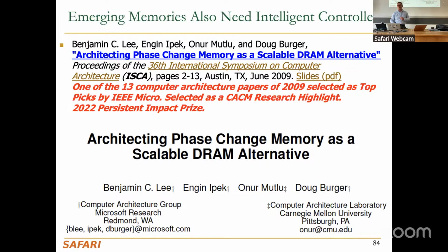But don't think that they don't run into scaling issues. All memory technologies run into scaling issues at some point. And some of these technologies have not been examined as much, have not been pushed to the limits as much. We have kind of pushed DRAM and flash memory to the limits. We still keep pushing them to the limit by reducing the cell size. But some of these memory technologies that are investigated, both in industry and academia, they start with large cell sizes. As a result, people may not see those vulnerabilities early on. The question is, what happens if you actually scale to very small cell sizes that actually enable the capacities that we have today? Okay, so we're going to have fun with the emerging memory technologies lectures, I think.